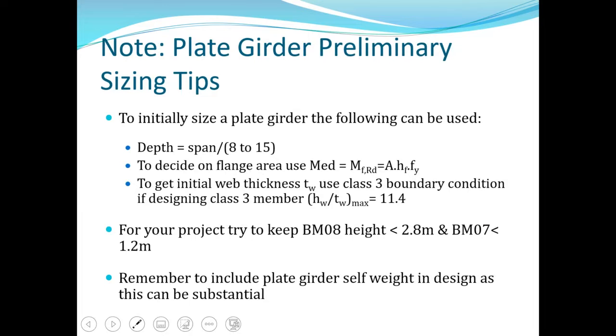Next tip to keep an eye out for: you're trying to size up your plate girder for your project. So where do we start? In the two examples I've done, I gave you a plate girder size to start with and then worked out whether it was adequate to carry the loads or demand on it. But usually in design we don't know what size to start off with, so we have to make some sort of guesstimate of the initial size of a plate girder. And these are my tips for getting the initial size.